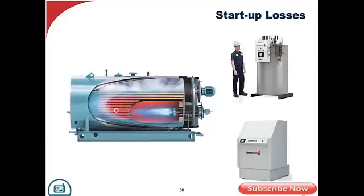But don't forget one other thing about this. Once this boiler comes up to pressure, it has a lot of thermal mass. It's got possibly a lot of refractory, a lot of residual heat. So once it comes up to temperature, even when that burner cycles off, it continues to steam. And I don't think anybody would disagree that a boiler that's not firing is more efficient than anything.